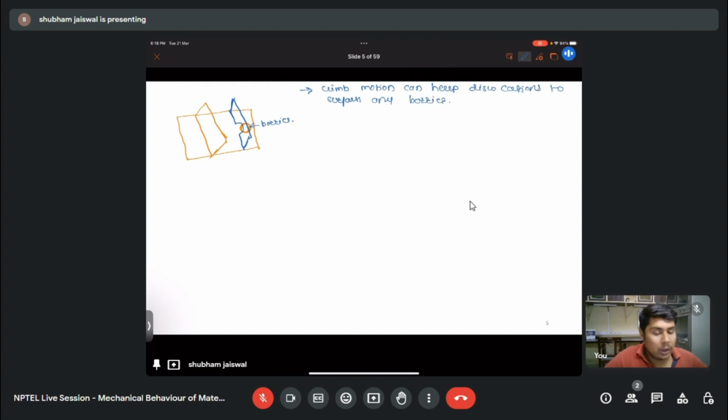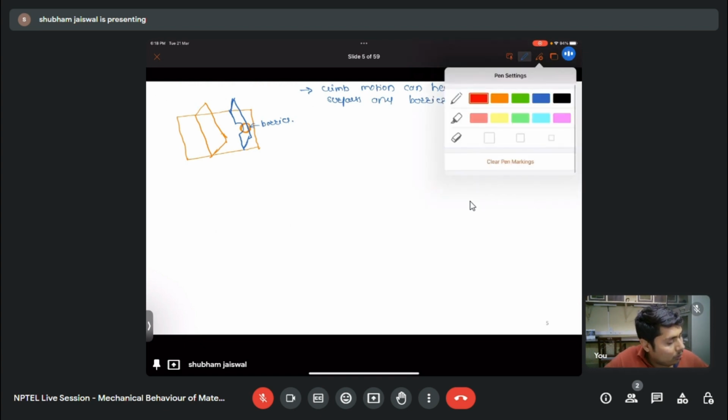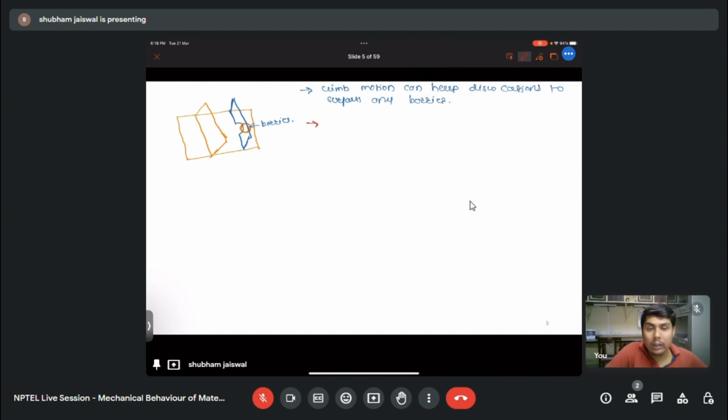Okay. So as we are talking about the vacancy in the climb process, generally the vacancy diffusion is temperature dependent. So this mechanism is only active at higher temperature, and the activation energy of diffusion is nothing but the vacancy diffusion barrier.